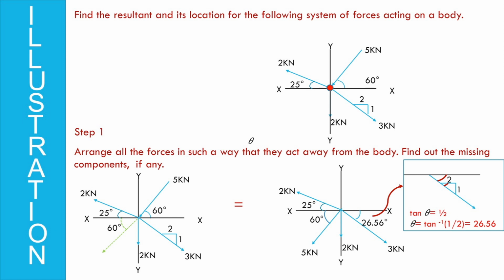Now, how are we going to resolve this? The first thing that we have to consider is that we have to convert all the pushing forces into pulling forces. That is, all the forces should act away from the center, away from the object. The next thing is, if there are any missing components like finding out the angle or finding out the force, we need to do that first.